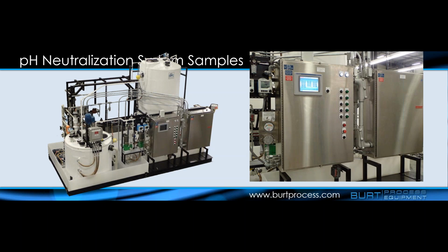So if you have a 10 or 15%, say, acid that can go into a tank, be treated to neutral. And those systems always have built-in heat exchangers because you end up with a very exothermic case. I don't remember off the top of my head, I believe it's like 54 kilojoules per mole of reaction going off with those applications.